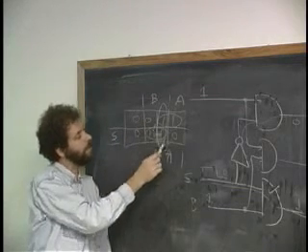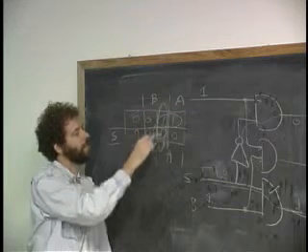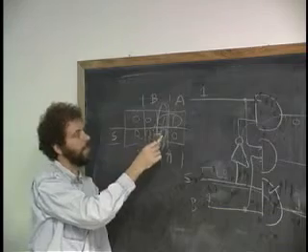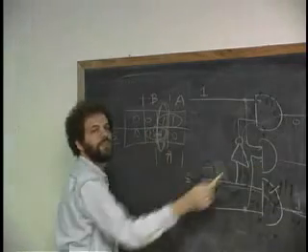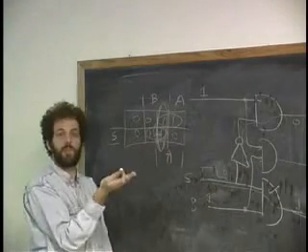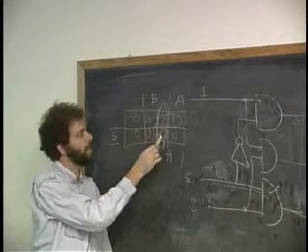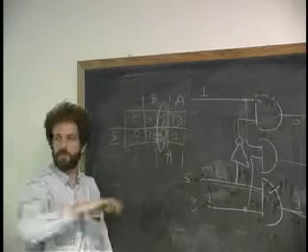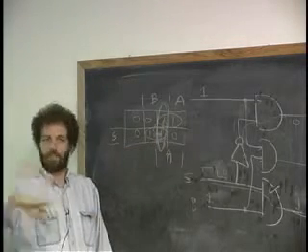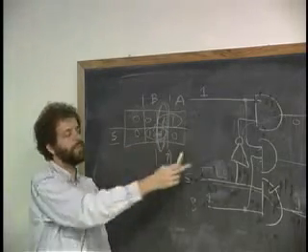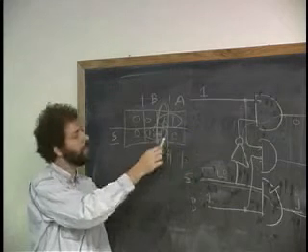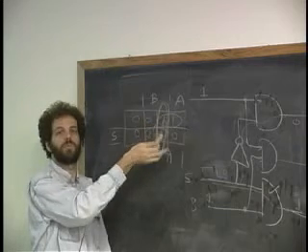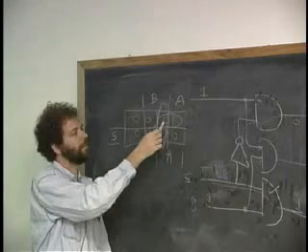So I fixed the problem by adding another island here, which doesn't care about S. And so when I transit from this state to that state, this middle gate isn't even looking at S. And so it is responsible, and it holds the output up, irrespective of the transition that's happening here. And I can take forever to make this switch. It can be a very slow slope. It can oscillate up and down. Doesn't matter. The wire doesn't even go to the gate. That's what it means to have a circle that has more than one 1 in it. It means that we're eliminating inputs from the product term.